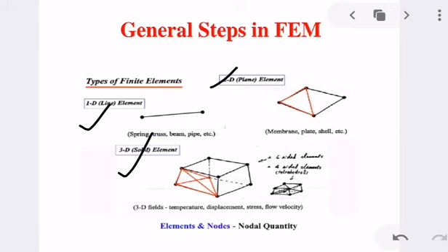One-dimensional element, also referred to as line elements, is often used to represent members which are too long compared to the measurement of the cross section. Two-dimensional elements are also referred to as shell elements or plane elements, which are often used when thin sheet structures are under bending deformation. And three-dimensional elements are also referred to as solid elements, since actual tasks deal with the three-dimensional model using CAD. They are used in analysis the most.